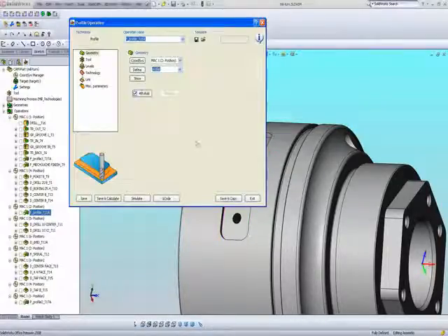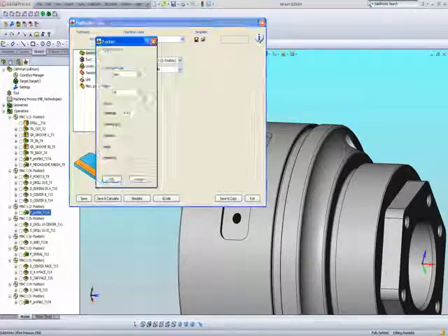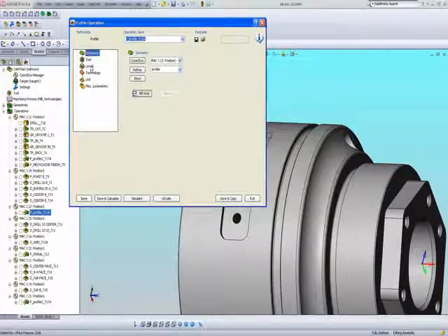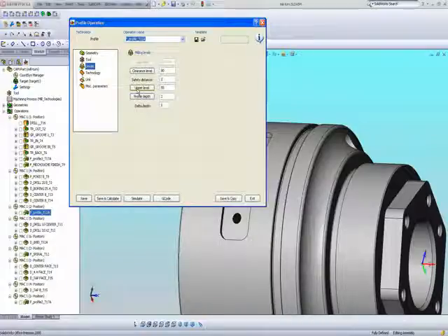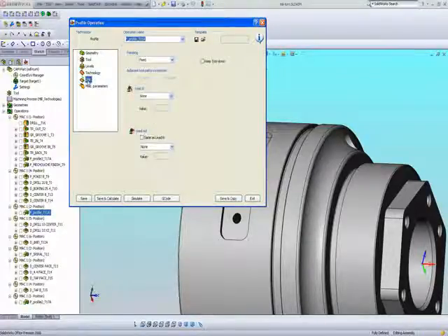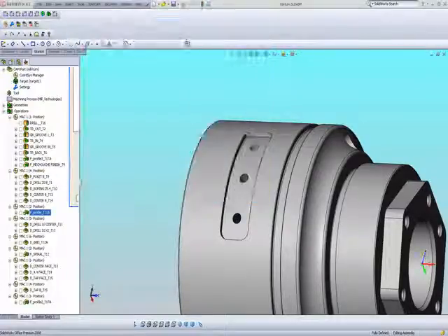But one more thing we should also notice, even besides that, is that we're using fourth axis. And the coordinate type will be split, working on the YZ plane. In my levels, I have my upper level, and I have my profile depth. And my technology is your typical, simple profile technology, doing a rough cut, doing a finish cut, links. Let me just do a quick simulation.